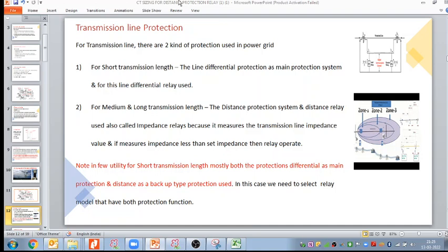We have made it unit protection forcefully by dividing the distance protection into zones. So zone one, we take only 80% of the line on our side and another 80% from the opposite side. So if the line length is very short, the fault may occur in the middle, and the relay may not be able to find out exactly where the fault is occurring because of the CT errors. So that is a problem.